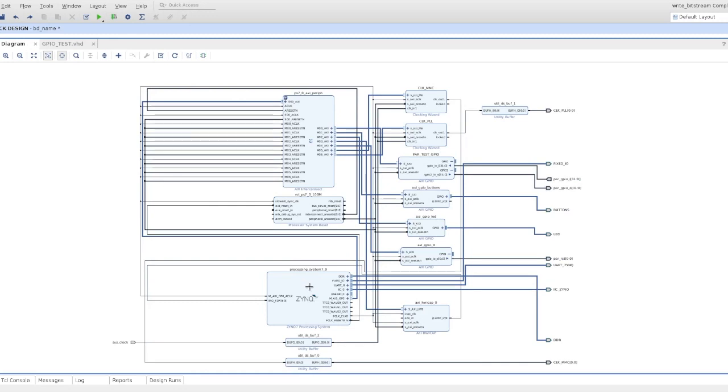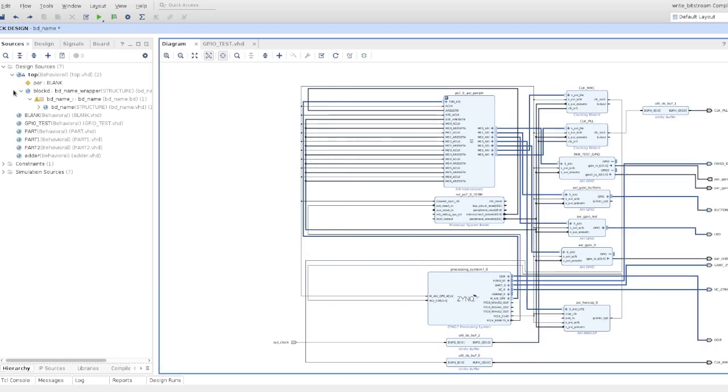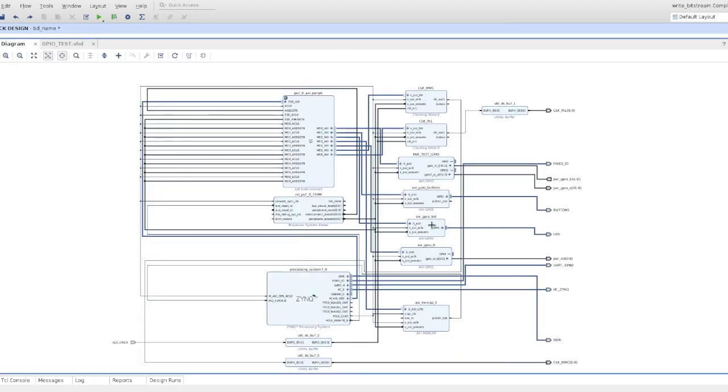It consists of a Zynq programmable system which is capable of controlling all existing AXI devices in this design. Actually, this also has a web server which provides a user interface. The hardware ICAP block is used to flash new bit streams into the partial design. This allows the Zynq to dynamically program the partial reconfiguration block, which is implemented in the project view.